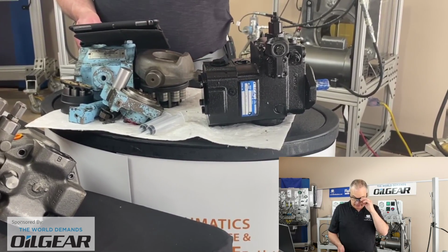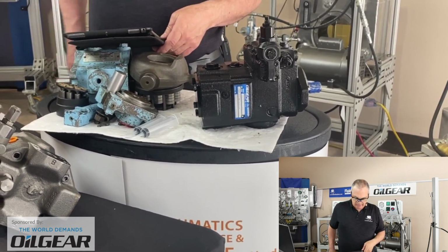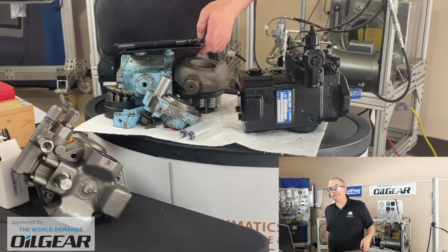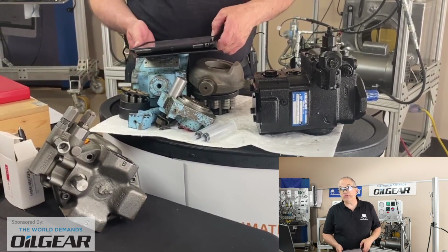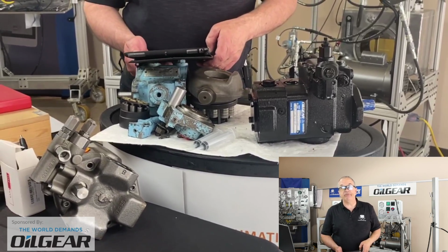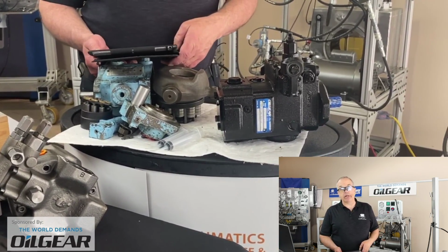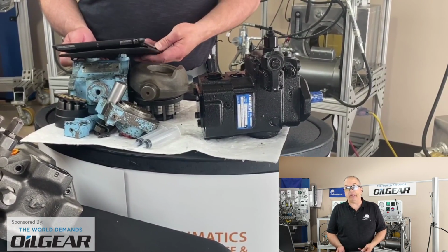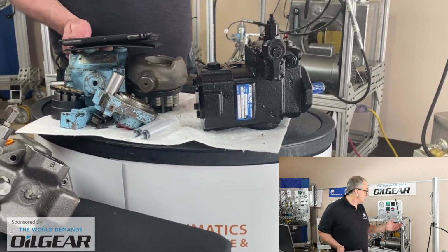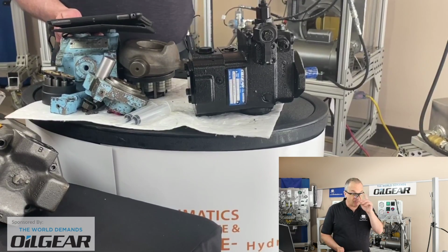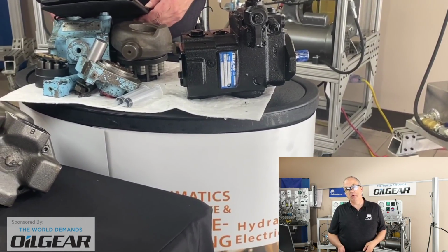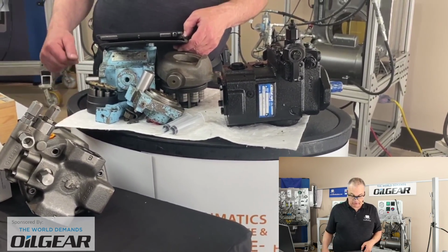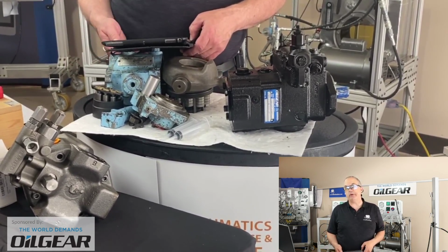Trigger Tech says, any advantage to a hybrid system that's using variable frequency drive motor and pressure pump? Yeah, well, variable frequency drive electric prime movers being hooked up to fixed displacement pumps is certainly a very common thing now. With electronic controls being what they are, a lot of opportunities are presented to save energy, and so that is becoming a very common package. I'm sure before long in our own training fleet we'll have a fixed displacement pump driven by a variable frequency drive motor. But I think you're asking about a variable frequency drive motor together with a variable displacement pump, a pressure compensated pump. Not as common.